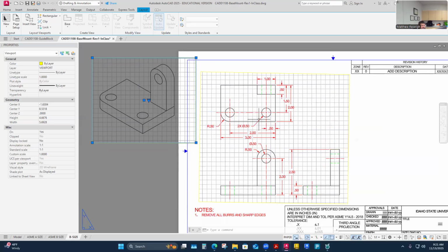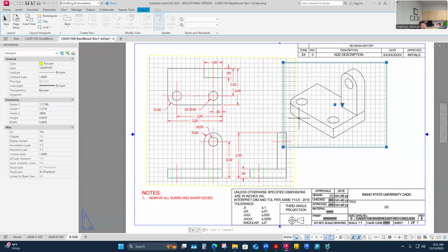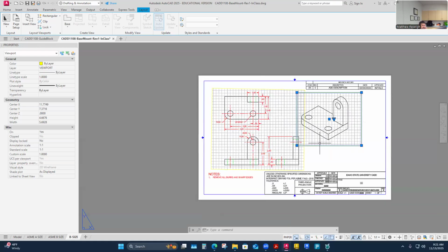I would have come from this side, maybe with the hard radius towards me right here, and then away. So I just feel like there is a better place to place this, so it makes sense with your other views. It drives the reader of your prints to make that alignment in their brain. So if that makes sense to you, yeah, I think I would have. Placing it over here, I'd almost be looking at this round corner as drawn from that perspective.